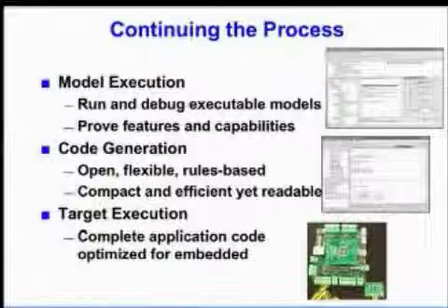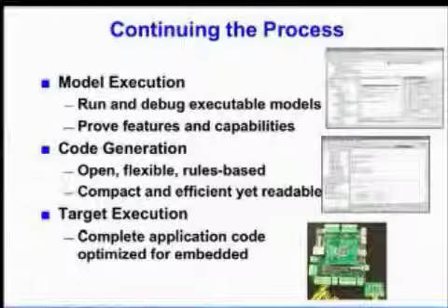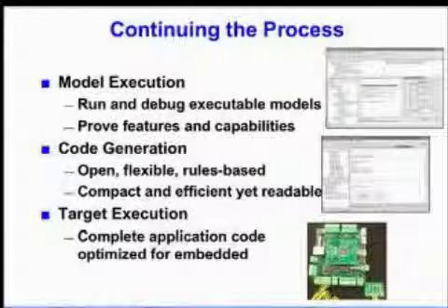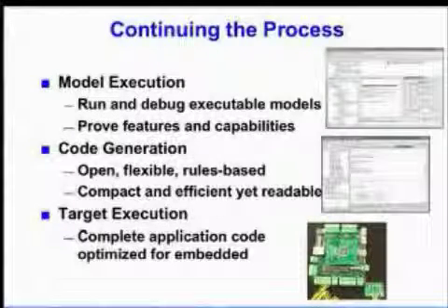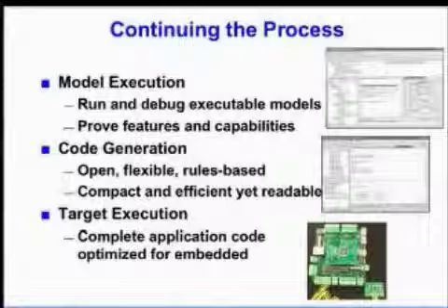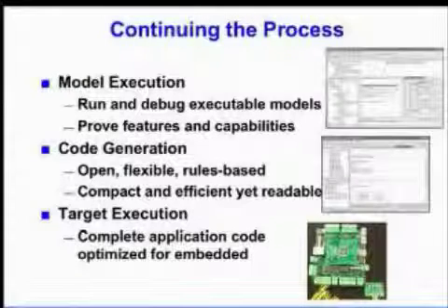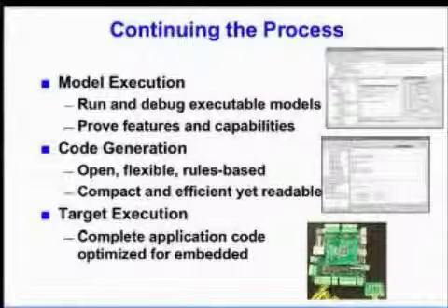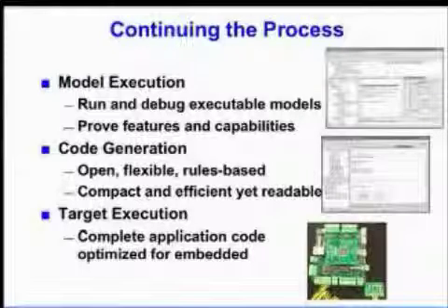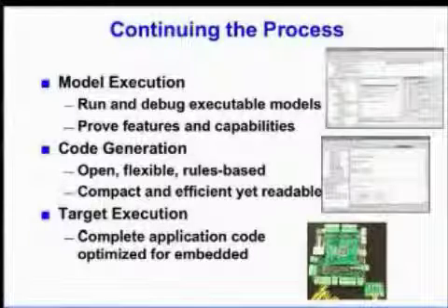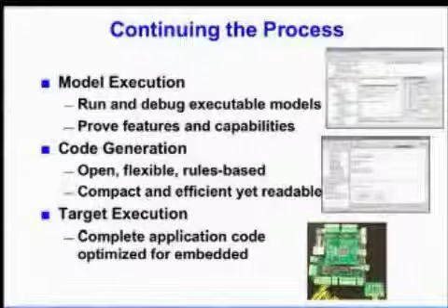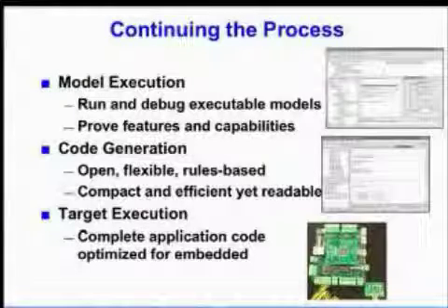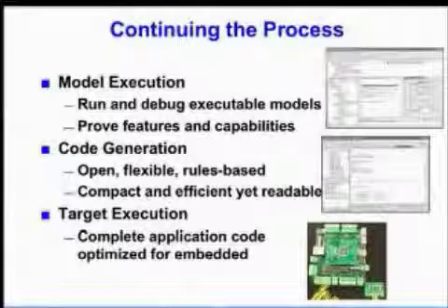Let's continue the process. We have now built a platform independent model of GPS data acquisition. We've gone through and broken the application into individual components. We've modeled those components using the class diagrams, state models, and action language. Now I would like to verify that my application is correct and actually build it. So we'll continue the process by executing these models in an interpretive fashion using the model verifier portion of BridgePoint, after which we'll generate code and run it on the target.